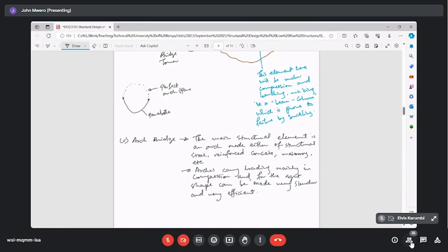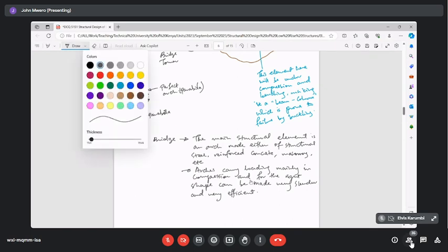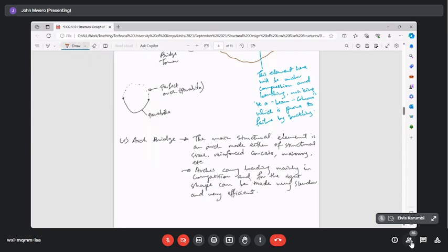The cable takes the most efficient shape to carry the loading in tension. If you were to flip that, then it gives you the most efficient shape to carry loading in compression. And that will be pure compression. That will be the perfect arch. So that's why I'm saying, and for the right shape, that's why I've written here for the right shape, because for example, if you build a semicircular arch, it's not a perfect parabola.